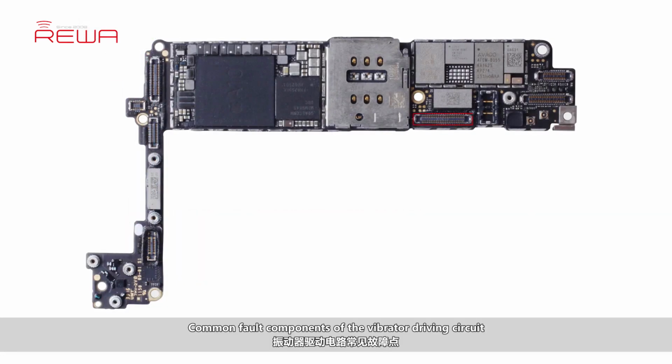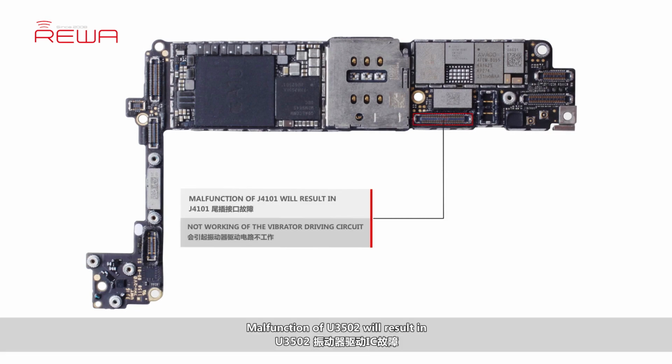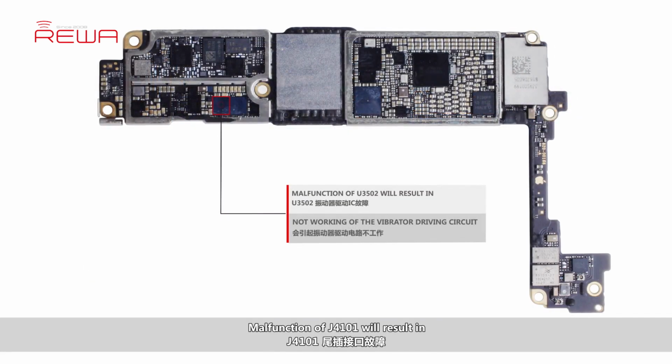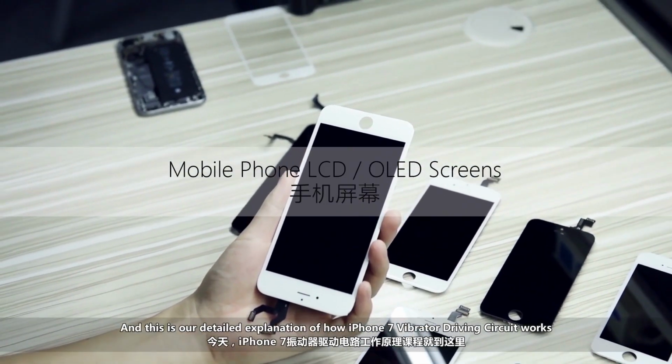Common fault components of the vibrator driving circuit. Malfunction of U3502 will result in not working of the vibrator driving circuit. Malfunction of J4101 will result in not working of the vibrator driving circuit. And this is our detailed explanation of how iPhone 7 vibrator driving circuit works.